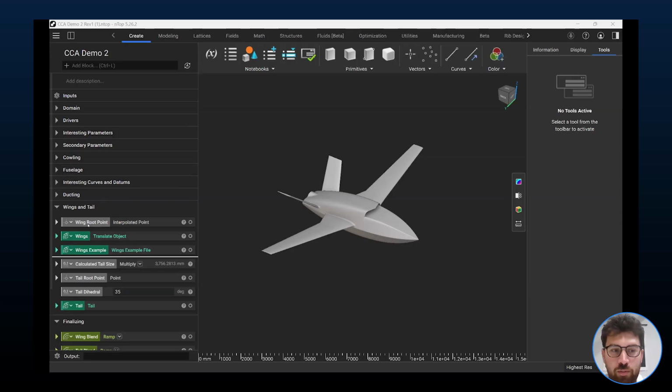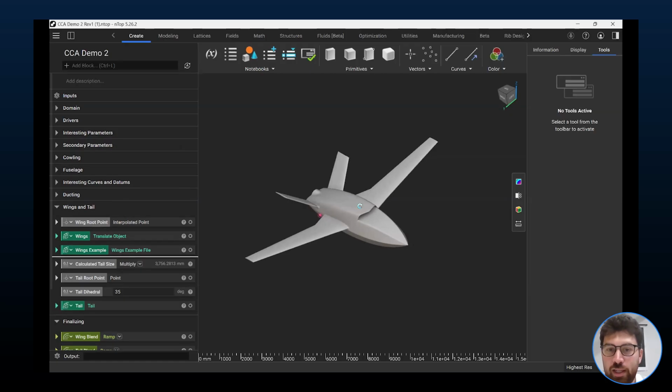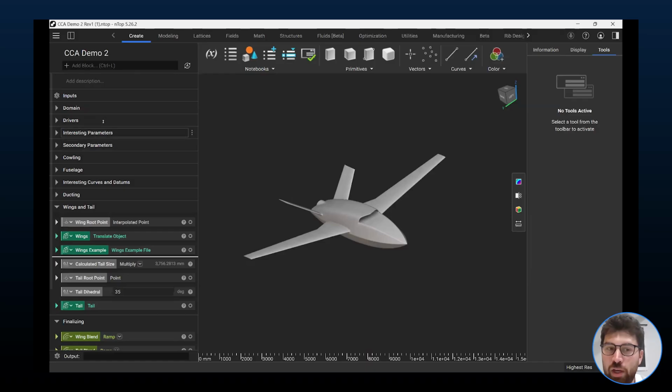For my part of the demo, we're going to go through our wings file, and learn the techniques we can use to create a single or double paneled wing, how easily we can adjust these parameters, and how to change the twist and dihedral of our wing as well. If you've never seen nTop before, I know we have some new people today: the 3D viewport at the center of our screen is where we'll view all of the output generated from the notebook on the left. In the notebook, we have a series of functions that calculate and distill all of this information in the viewport.